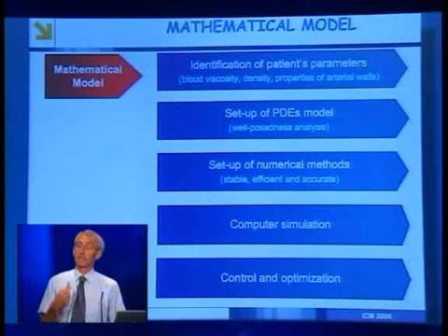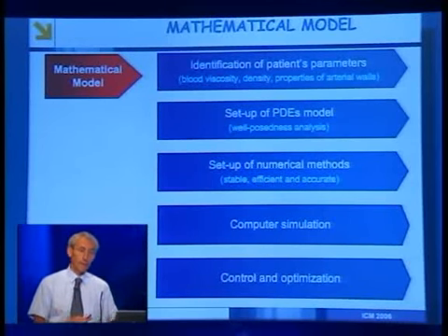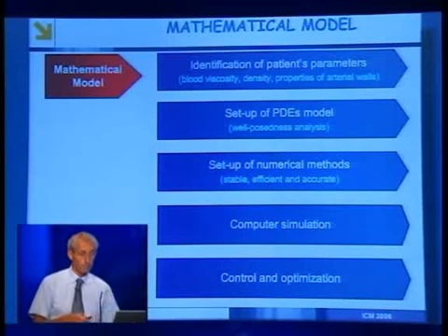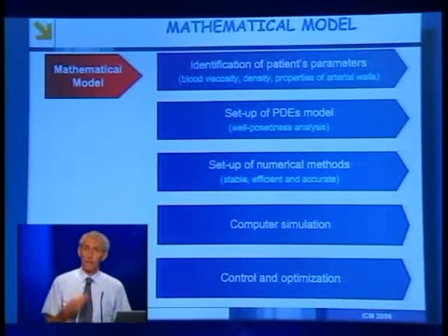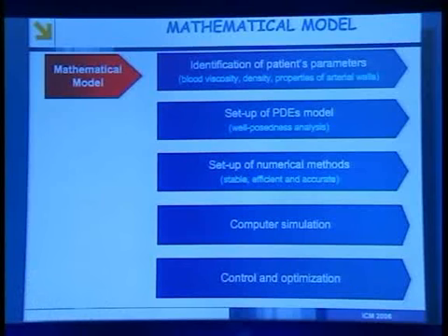You want a method which is stable, which means that it depends smoothly, regularly on the data, in particular on the numerical data, the grid spacing and the time spacing, say, the time step, which is efficient to allow you to obtain the solution in a reasonable time, not to wait for months, to wait for days, or hopefully to wait for hours. I'm not saying minutes because these are quite complex problems, and accurate enough to make sure that eventually you have a solution that resembles the real solution, the physical solution, say.